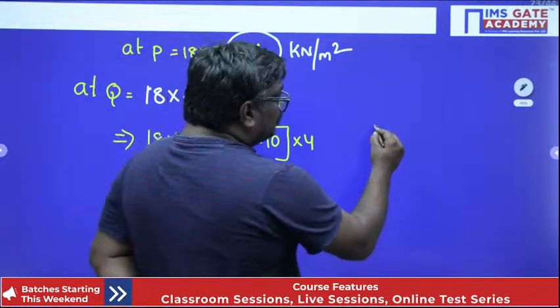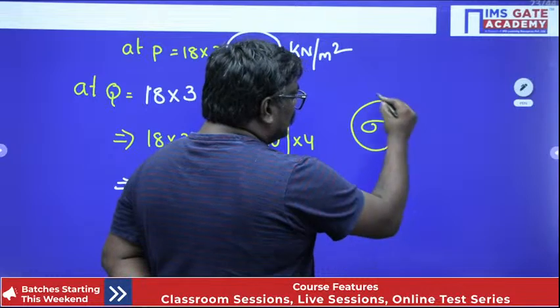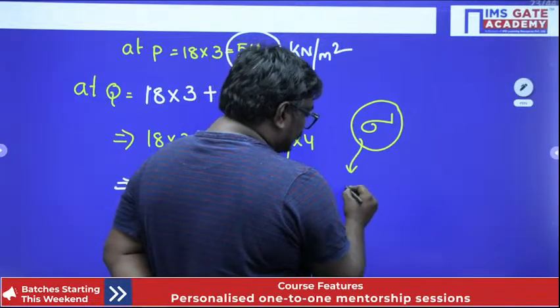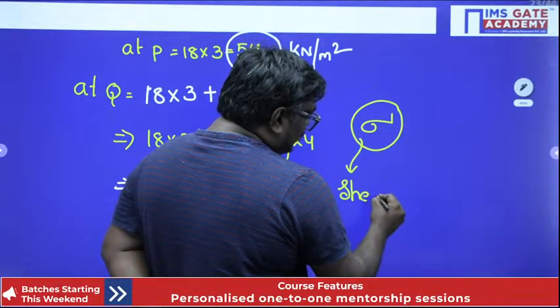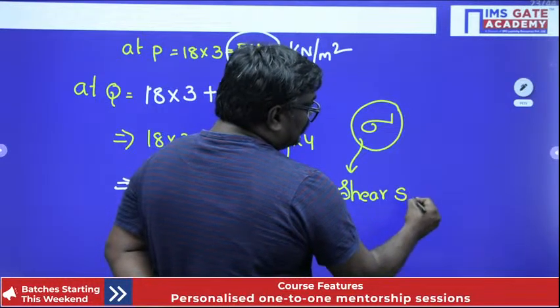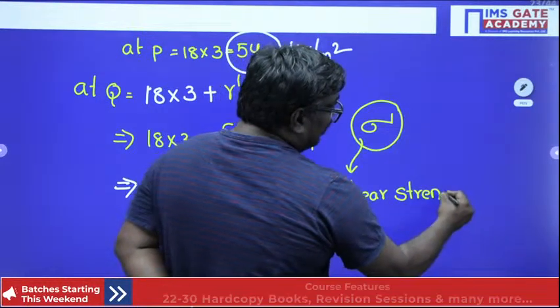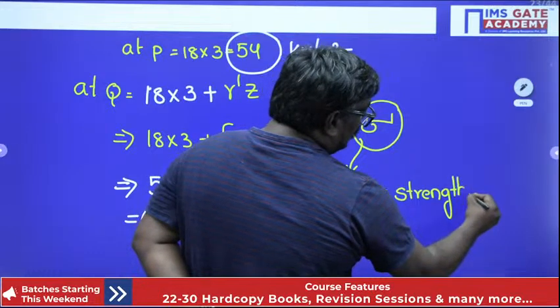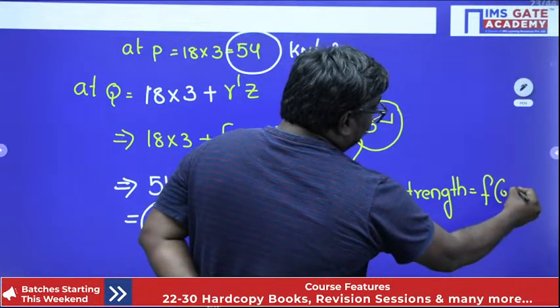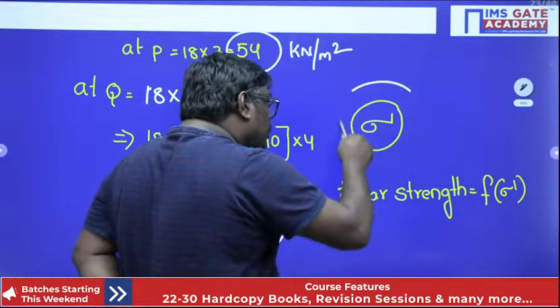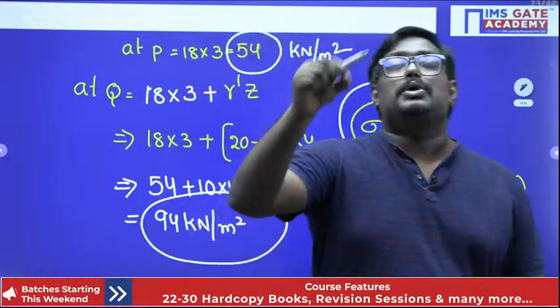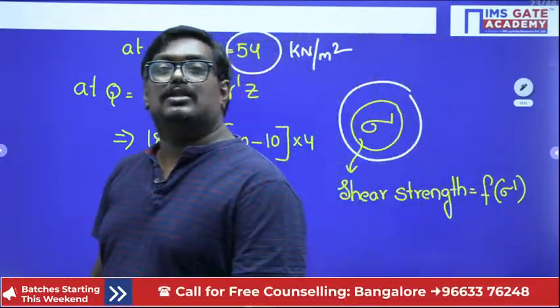Why do you want to understand effective stress, sir? If you want to calculate shear strength. Actually, my dear students, shear strength is a function of effective stress. Okay? If you don't know effective stress, you cannot estimate the shear strength of the soil.